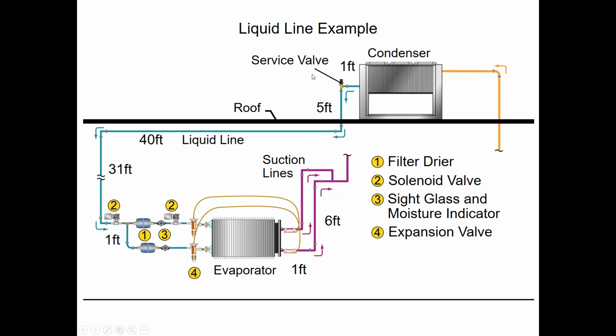But so those are sensitive. You get into screw compression, like on our chillers, for instance, the 30HXs, HXA, HXCs. Those are going to have anywhere from 5 to 7 gallons per circuit in them.